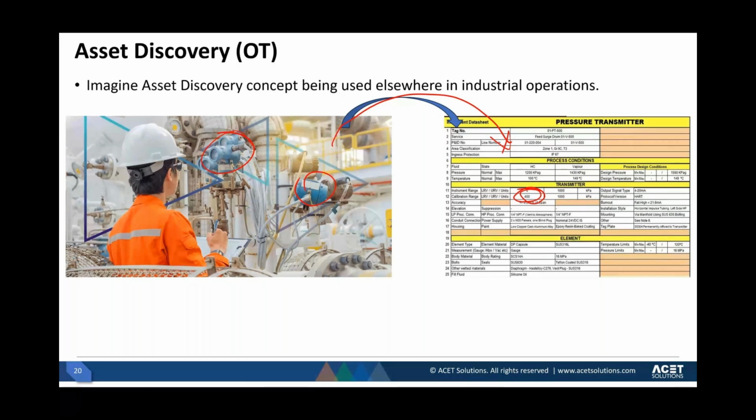So that means we're assuming that somebody makes the changes to the field instrumentation, and then weekly or monthly, whichever way, manually or automatically, you discover those changes and you bring it back and update the documentation. You would still have an updated as-built documentation, no doubt about that, but that violates the very basic principle of change management. This approach would never be allowed in any modern industrial facility, that the change is made first and then the documentation is updated to reflect the change.